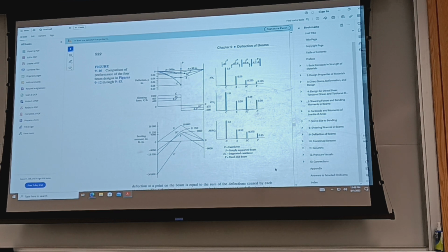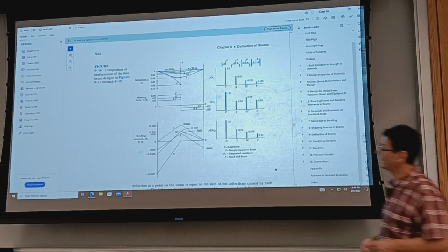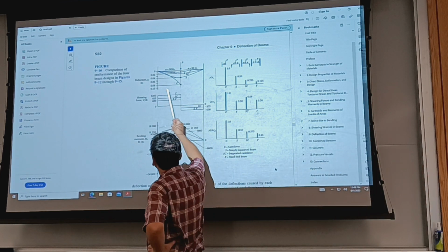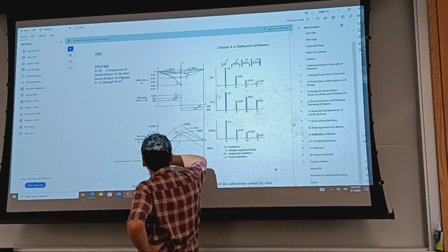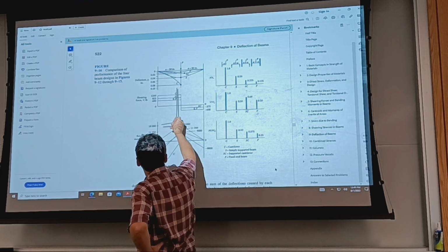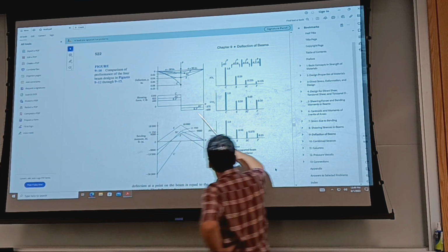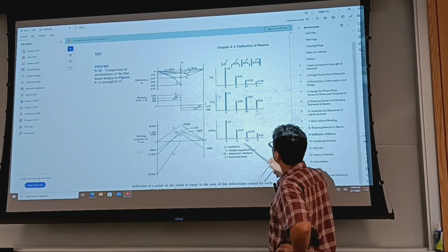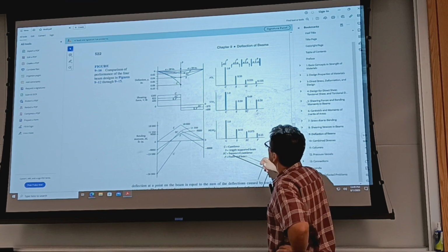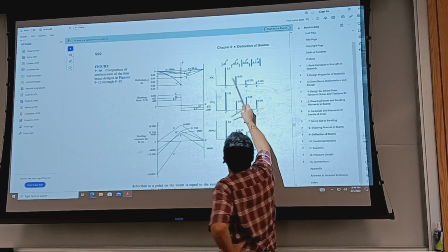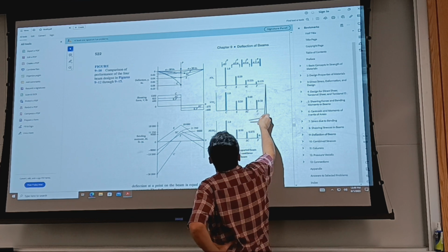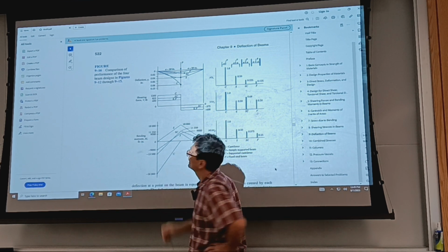Relevant information if you design with a beam and you want to minimize deflection. Again, the overhanging beams or cantilevers are not good when it comes to deflection, by far, you can see here. So everything else is like 1/2, quarter, and 1/8. Okay.